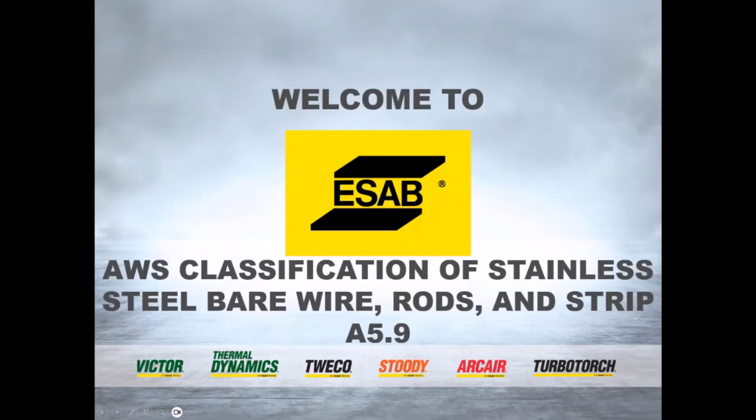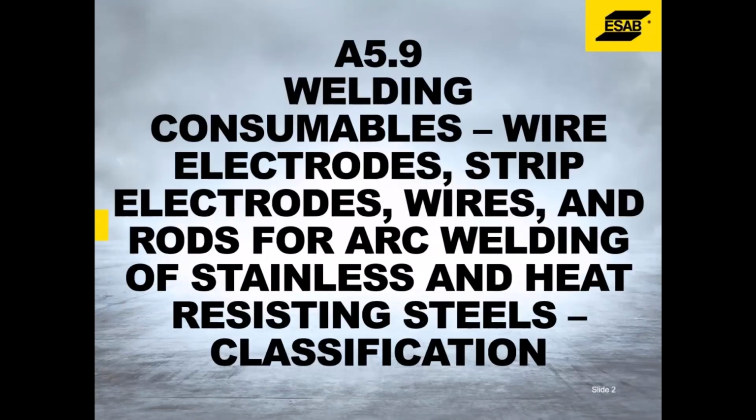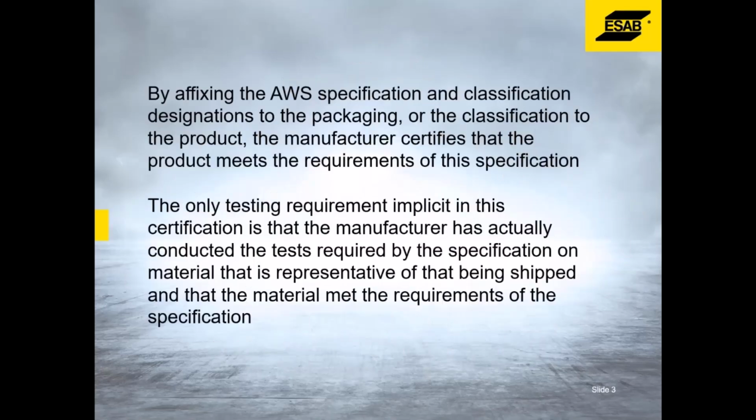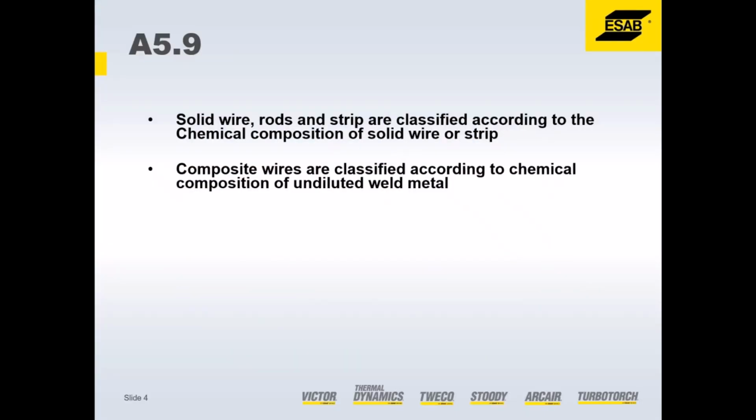Finally, we're going to go through solid wire stainless here. So again, just like with stick rods, we are going to be basing these off of chemical compositions. And there are not going to be any tensile strength requirements in this specification. It is purely chemical composition.